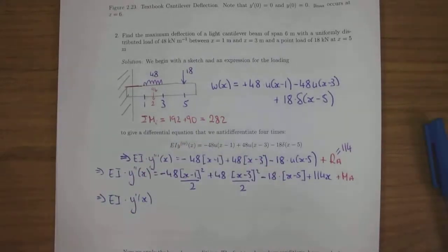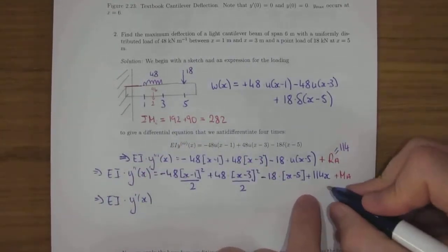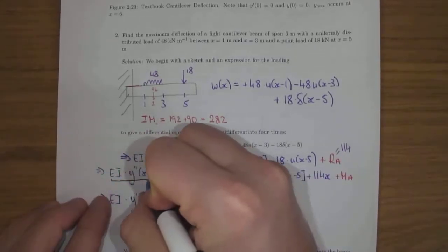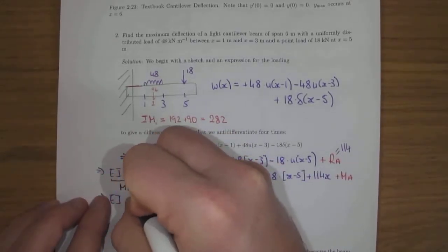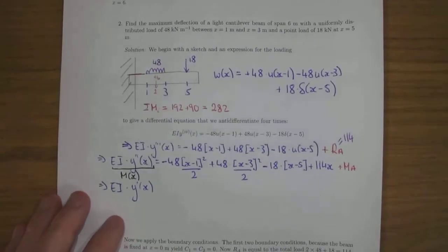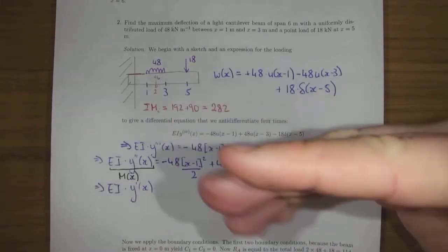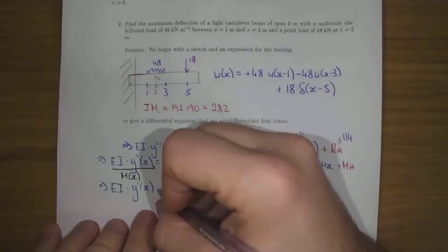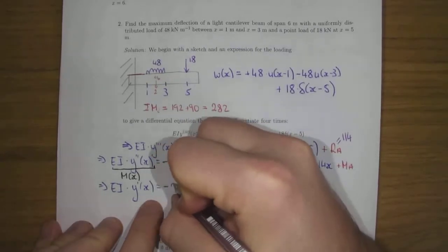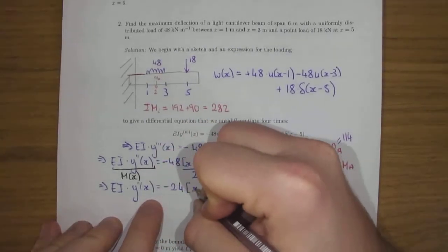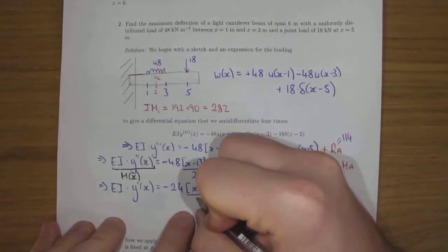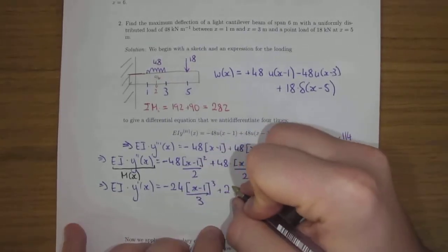Well, it's probably worth pointing out that this whole thing is the same as the bending moment, EI times the second derivative of deflection. One of the things I'm going to see is confusing bending moment and deflection. They're not the same thing. Deflection is the beam being below neutral, and the bending moment is the bending moment. Not the same. Minus 48 over 2 is minus 24, and it's where some of you will lose marks on the second assignment. 48 over 2, 24.